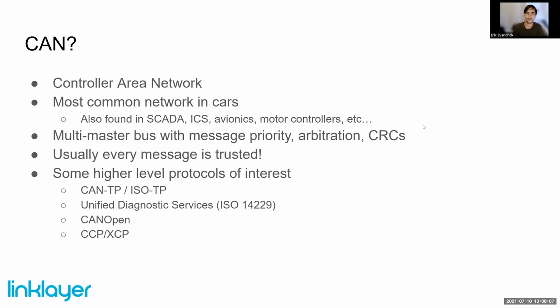This has led to a bunch of good demos and attacks, but the way I look at this now is that if an attacker has the ability to send arbitrary frames on a CANBus, it's like having root or ring zero access. It's that very high-level privileged access, so it's compromised. That being said, there are some mitigations in the works for those types of things.